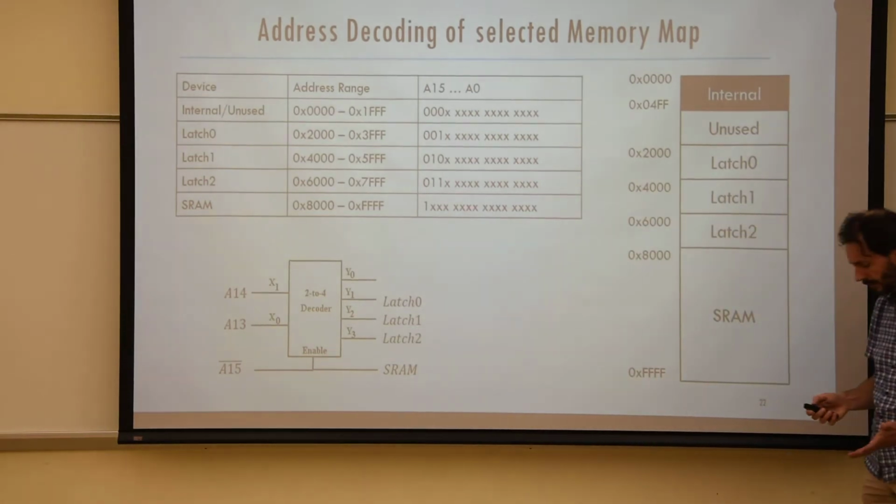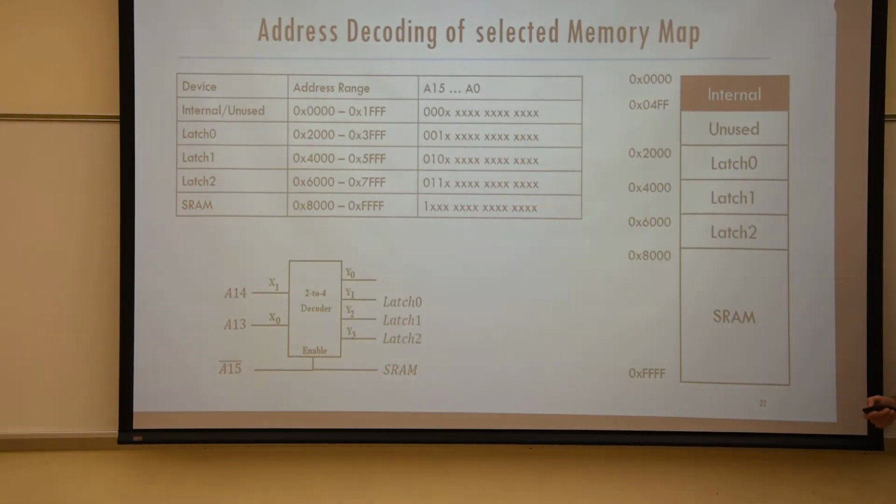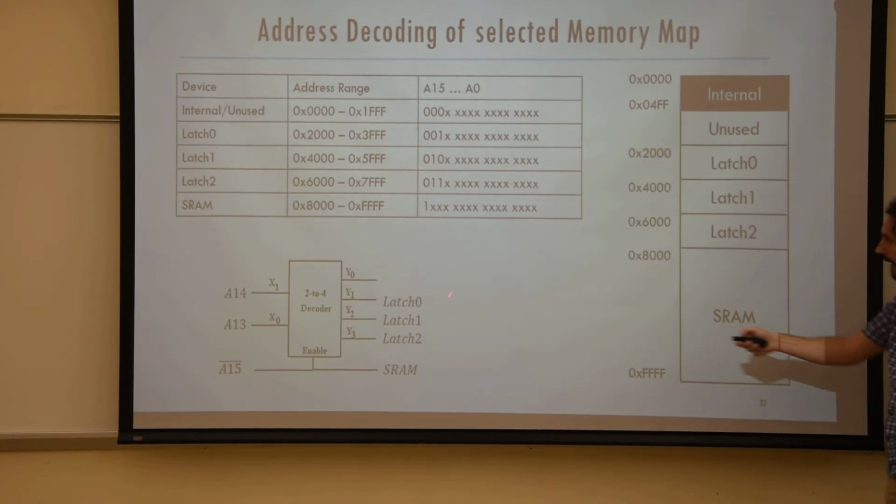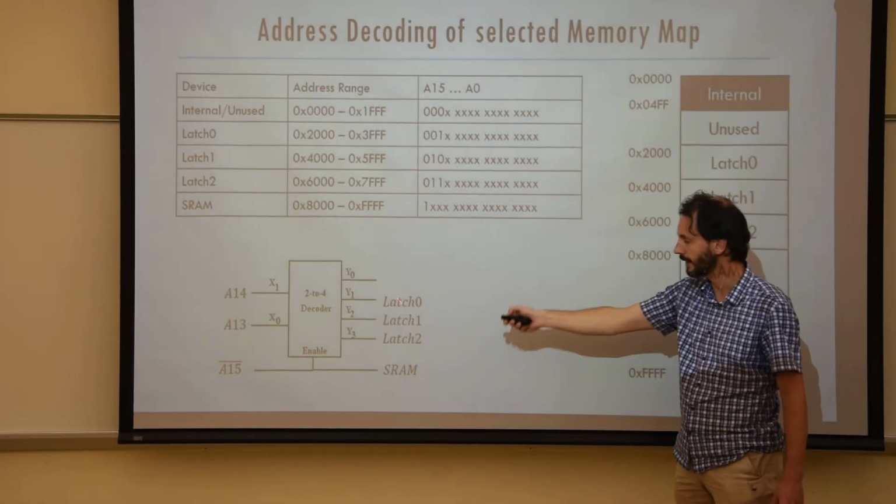Now notice I'm only storing 1 byte in those 8 bits, right? That's just 1 byte, that's it. But I have just given this latch a whole range of addresses that are all associated with this latch 0. And that's the trick actually. By doing it like that, I build a very simple decoder.